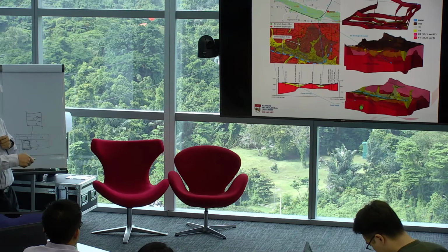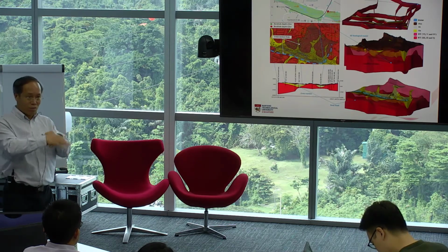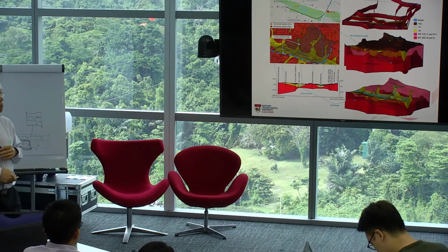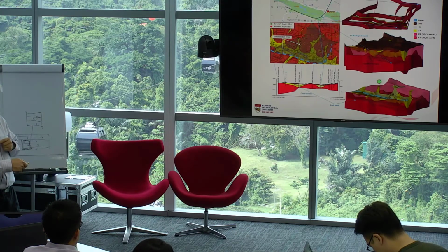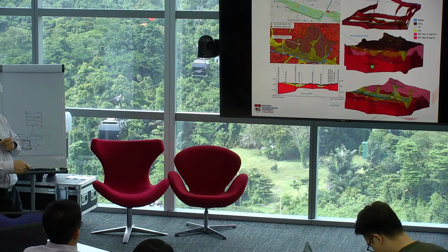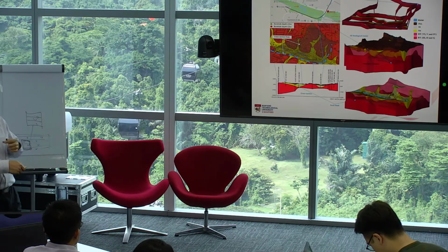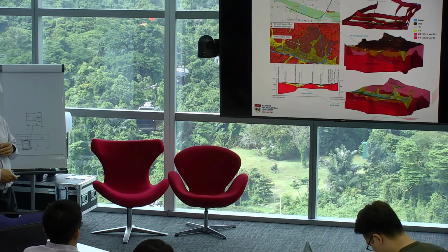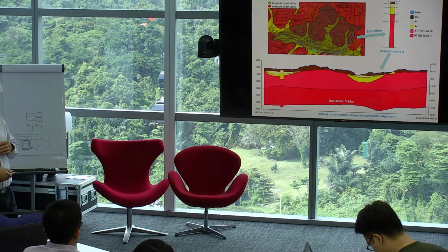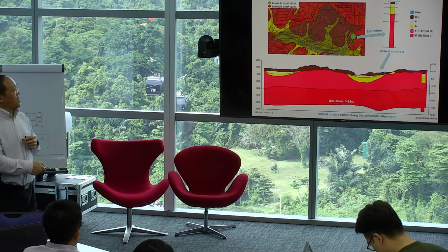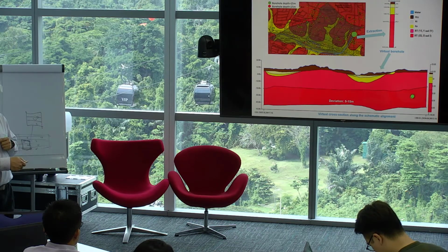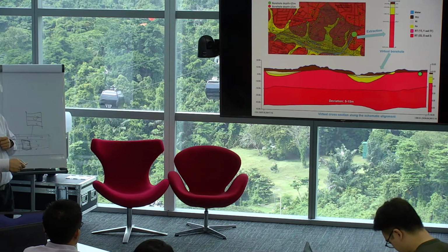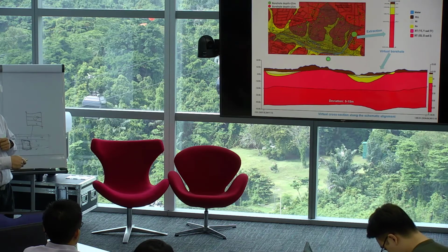Even within the Bukit Timah granite, you want to know the weathering depths. From there you will have informed information on how deep your tunnel or your station should be. Let's say we don't have any new borehole data yet, and just make use of the model, we could construct the cross-section along the MRT alignment as shown over here.